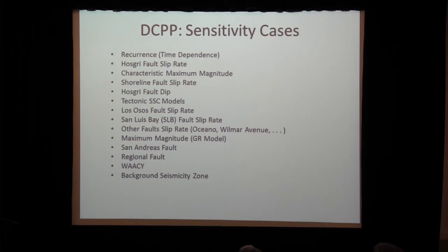If you also remember back to Norm's talk, the dip angle is going to change the distance relative to the plant. Our attenuation curves, our GMPEs, really saturate, they turn over, so those changes in dip angle probably won't be significant. I'm previewing things, but it won't be as significant in the sense that your GMPEs, your ground motion attenuation curves, are already saturating or turning over.